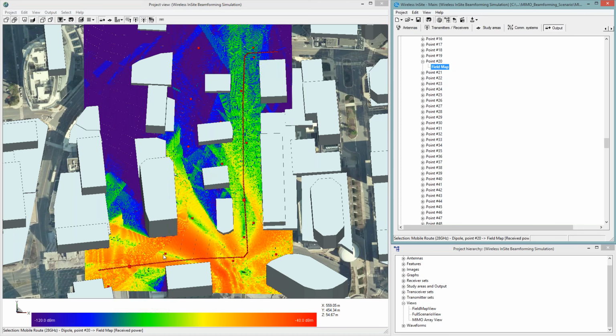If you look closely, you'll see that each of the other devices happens to be sitting within a null in the pattern. And so the zero forcing technique has made an attempt to minimize the interference to all of the other devices. The beam to our intended device is not quite as strong, but the interference to the other devices has been significantly reduced.